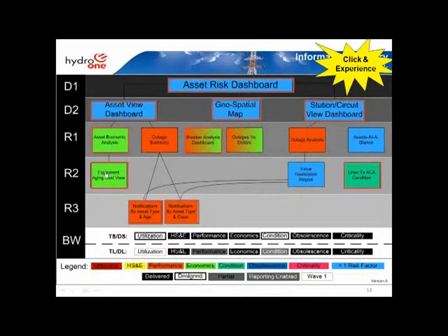So actually, there's a number of factors that are driving condition, all of which you mentioned. So some of them are online monitoring of transformers. We do the typical standard dissolved gas analysis on transformers. All of the standard tests that would drive condition, that would drive health, are those algorithms we're using and will be using in fully developing this dashboard. So we're using all of the industry standards, IEEE, as well as the asset condition health algorithms to derive condition.